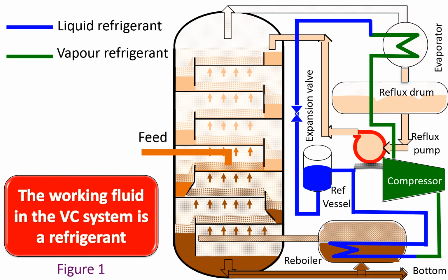The condenser needs a lower temperature refrigerant which vaporizes, taking the heat from the condensing overhead vapor. The vaporized refrigerant is compressed to a pressure just enough to condense the refrigerant. Vapor in the reboiler gives away the heat energy for boiling up the reboiler liquid, thereby condensing into liquid. The condensed refrigerant liquid flows to the buffer tank to start the cycle again.